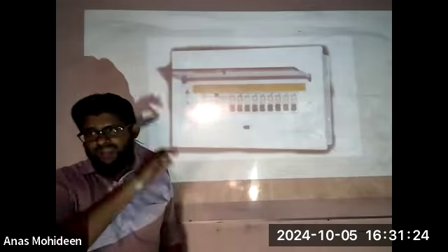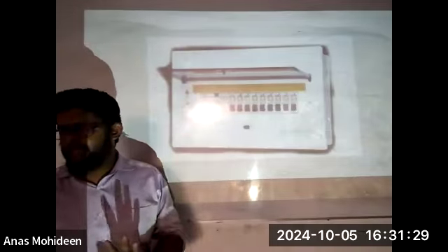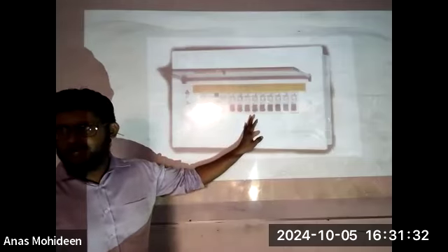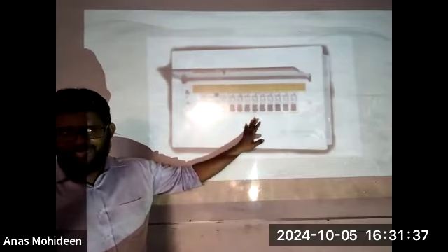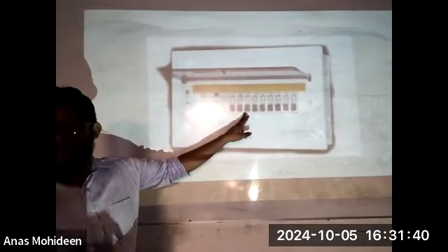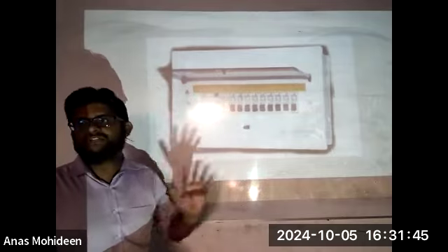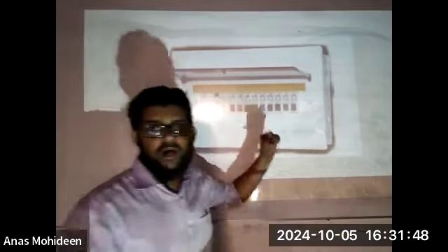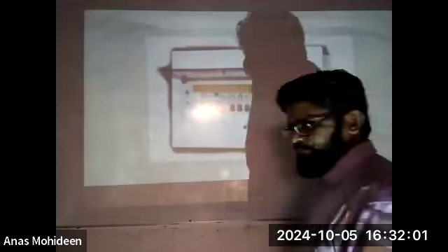Okay. And also don't play around. Don't flip the switches like a piano. Don't do that. One by one, just check it, but if you are checking, do it properly. Don't give me a bad name by doing it wrong. The main switch is the same. Don't just turn it on. Check if anything is connected. Otherwise, you will go wrong. Let's say the ceiling fan is on and at once you work the main switch. Again, it might stop working because of the sudden stop, with an unexpected result.